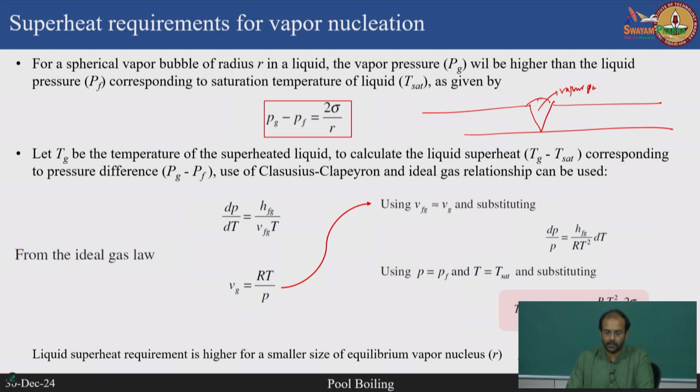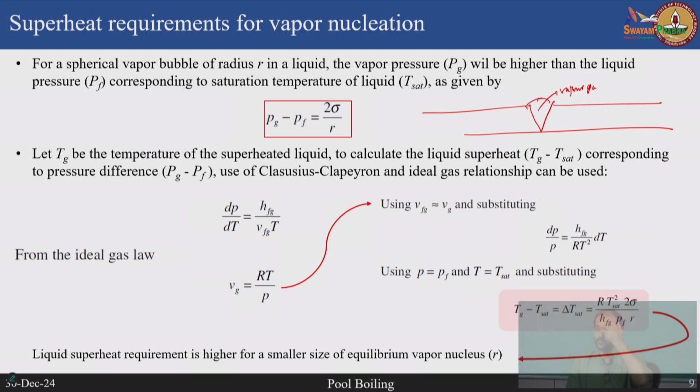So, where do these vapor pockets get created? They get created in these cavities where you have roughness. So, therefore, you can actually alter the nucleation characteristics by changing the surface characteristics, right. So, now if this vapor has to be created and nucleated, assuming that now you have a small micro bubble that is going to be generated within a cavity, it has to satisfy your Laplace-Young equation.